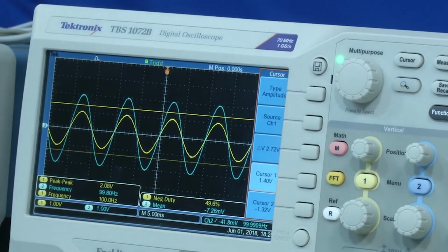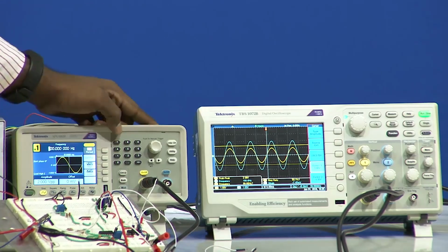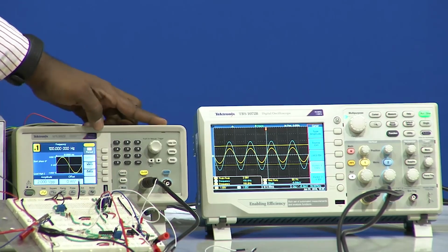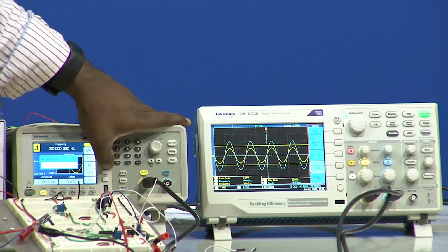Right now the frequency is at 100 hertz. I will slowly decrease it in units of 20 hertz till we are at 20 hertz. After that we will decrease to 10 hertz, then from 10 hertz slowly one by one increase, to see at what frequency the output voltage goes lower than the cutoff point that we set. So, I will set it to 80 right now.